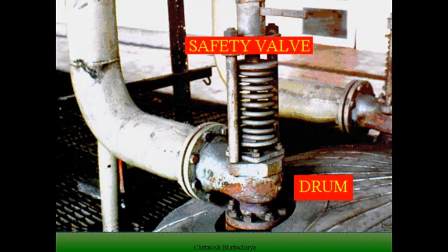All these safety valves together safeguard the boiler, and their total steam relieving capacity is more than the steam generation capacity of the boiler.